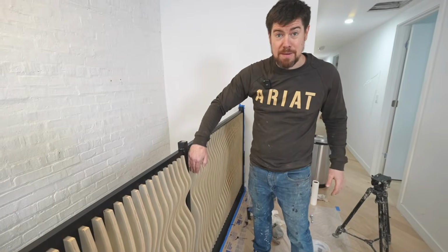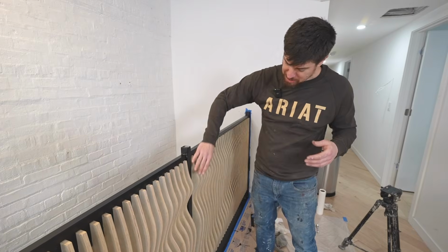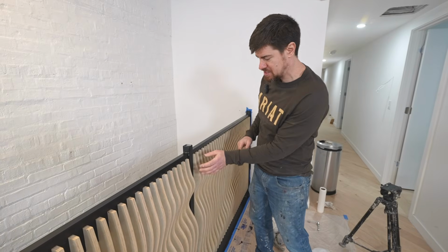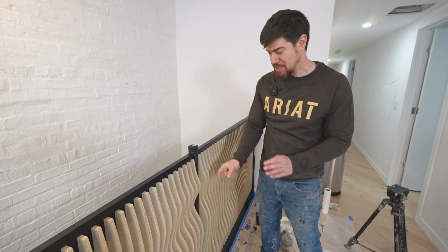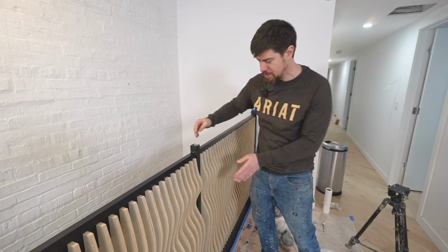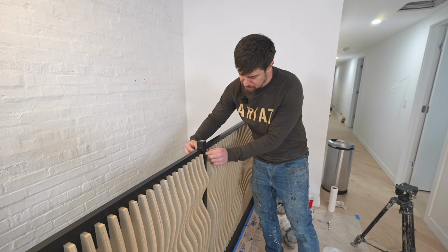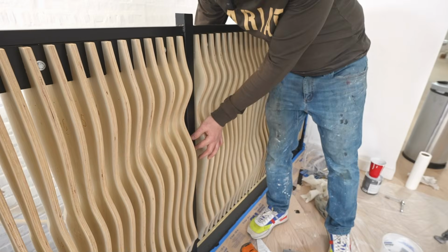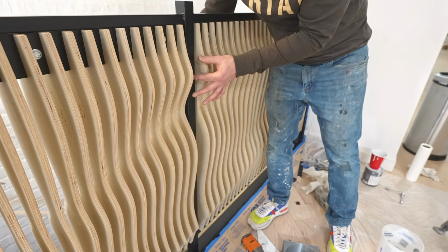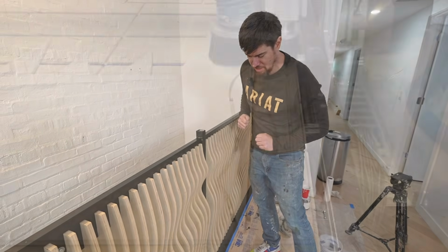There is this gap here. So what I think I'm gonna do here is create another slat that sort of interpolates halfway between these two pieces, slice 1.5 inches, the thickness of the post, out of the middle, and then basically use some epoxy to put that piece on so that it will be continuous across the middle post here.